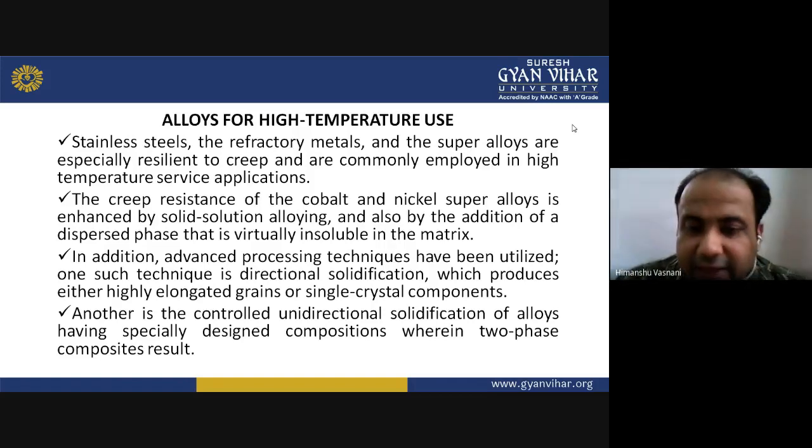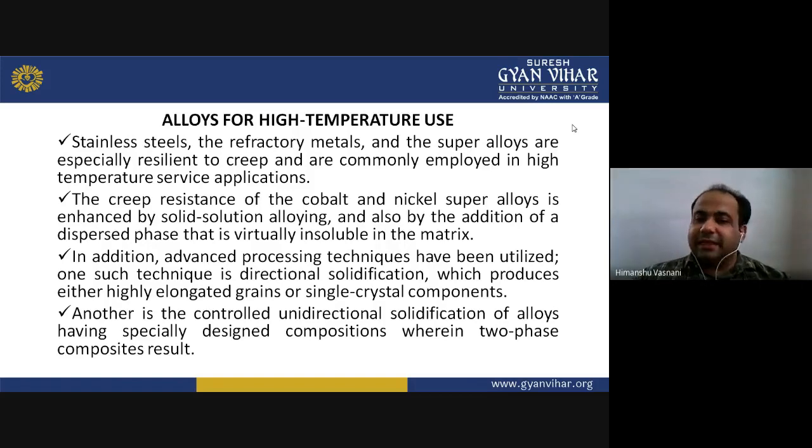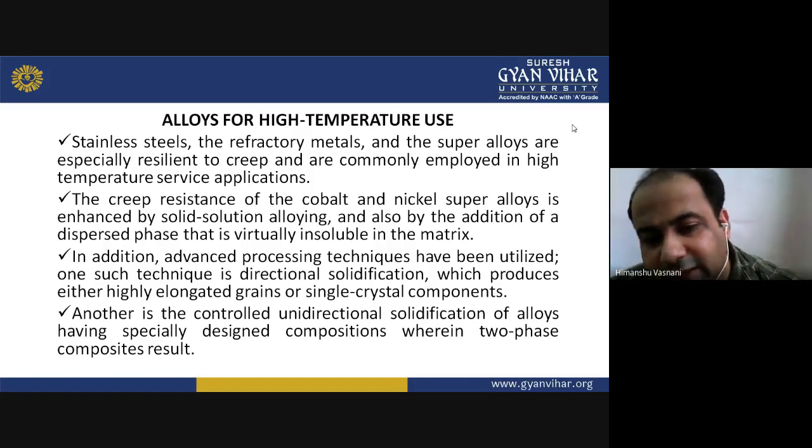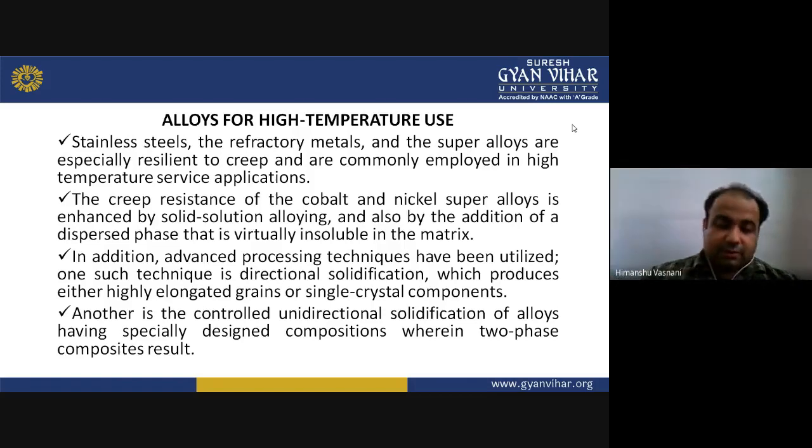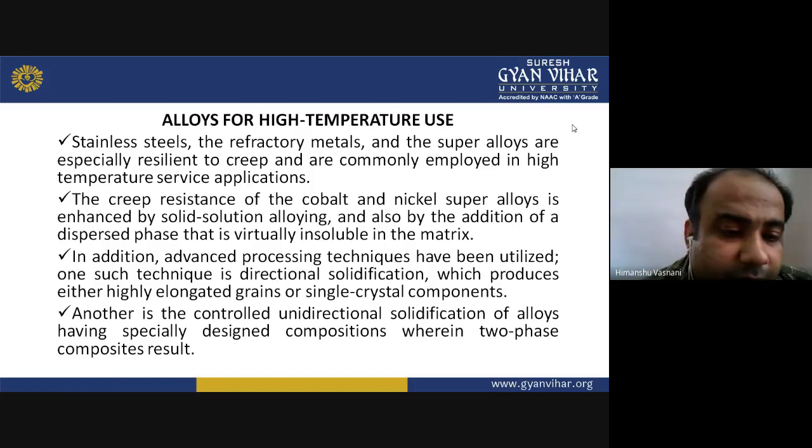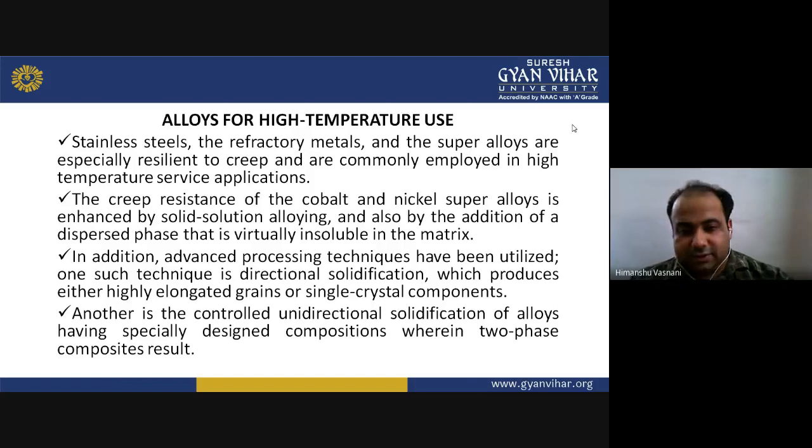One such technique is directional solidification, which produces either highly elongated grains or single crystal components. Another is the controlled unidirectional solidification of alloys having specially designed compositions, wherein a two-phase composite results.